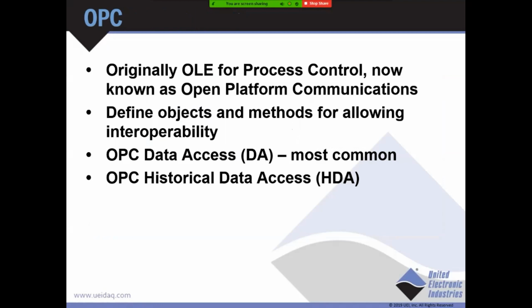So before we get into OPC-UA, it's good to see where it started from. And it started from just OPC. So originally, OPC stood for OLE for process control. So OLE, O-L-E, is a Windows system. It stands for object linking and embedding. Again, it is Windows specific, and it's usually used for linking and embedding documents, exchanging data between different applications. If anybody's familiar with DDE, Dynamic Data Exchange, that's part of the OLE subsystems.